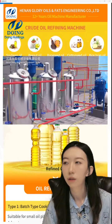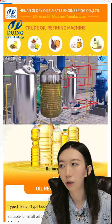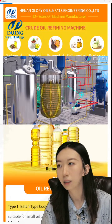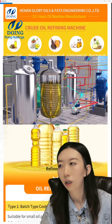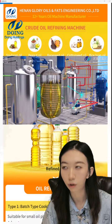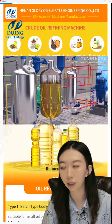And now we can see the deodorization step. In this step, we vacuumize the deodorization tank to prevent the oil from oxidizing.